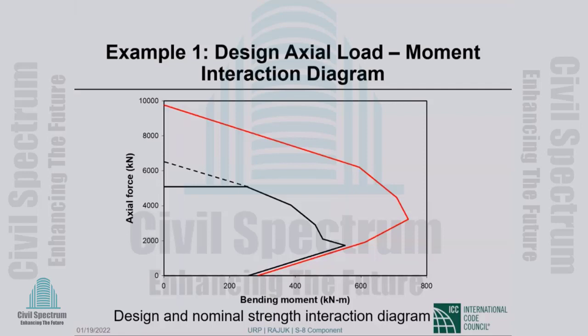There is nothing that tells you that reinforcement cannot be lower as you go down the building. It typically isn't, but for instance, if you increase the column section, then the reinforcement can decrease, and there is nothing against that. Maybe you have a slightly larger section at the lowest level. I don't know. But yeah, there is nothing against it.